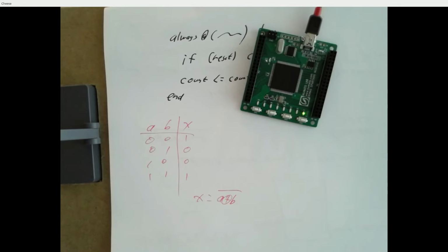Is that how dimming works? That's one way. That's one way that regular lights can be dimmed. It's also how a lot of motor control is done. When you want to control a motor with a microcontroller, usually you're either turning the motor on or off, right? And if it's on, it's spinning at full speed. If it's off, it's coasting. But by modulating the output, you can make it spin at variable speeds, and that's commonly done. So this is all stuff we'll do in summer if you're in 270. And that's fun stuff.